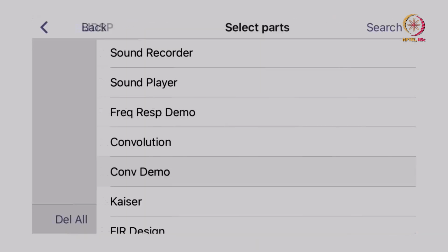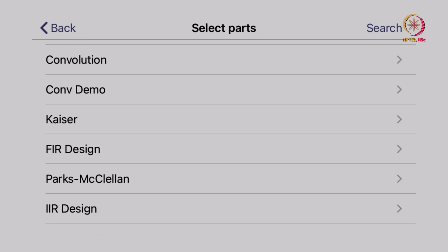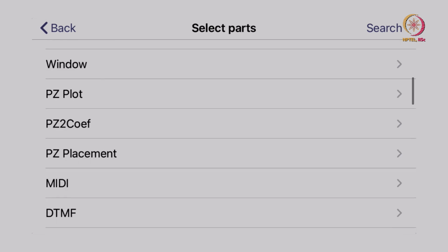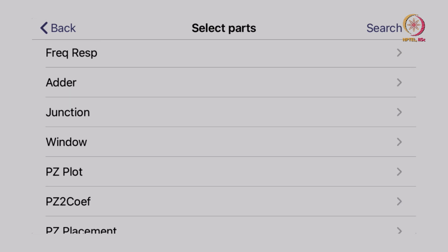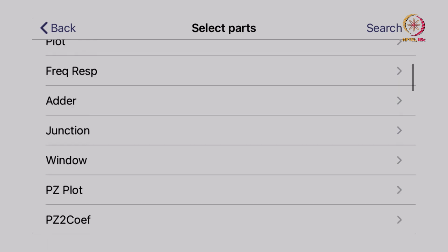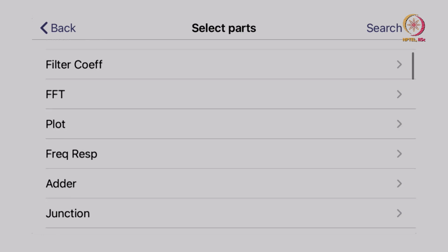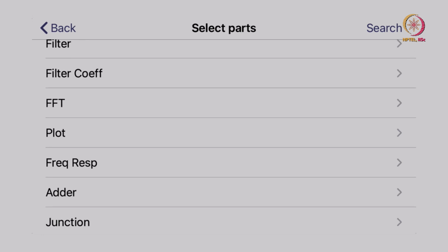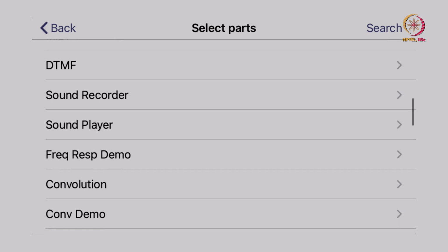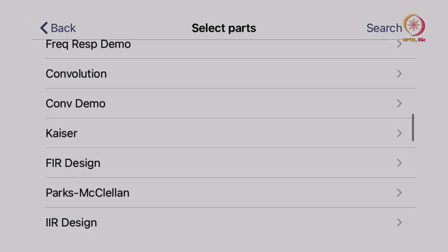Okay. So, the next one is if you want to design FIR, you can use it, or if you want to design an IIR filter, you can design it, but the FIR coefficient values have to be given from this block basically. If you want to design a window, you can do the window design, and you can get the frequency response, and the filter coefficients have to be fed into your filter design block basically. So, we will take up FIR filter design. So, I have asked for this.